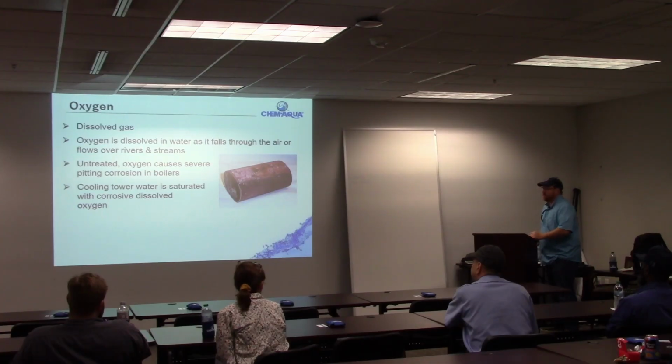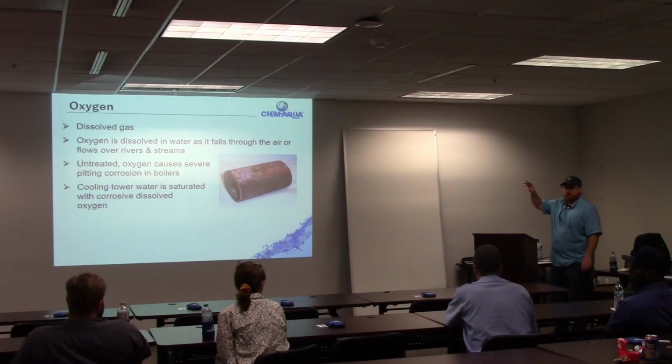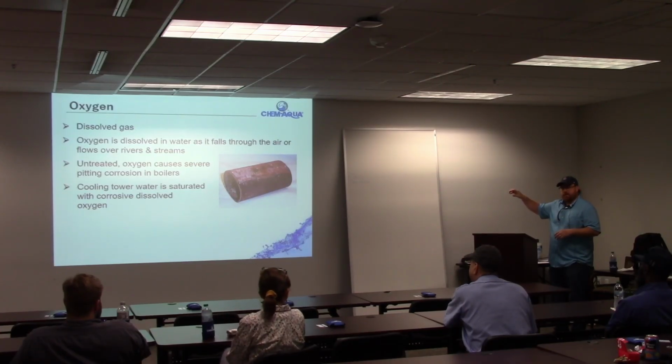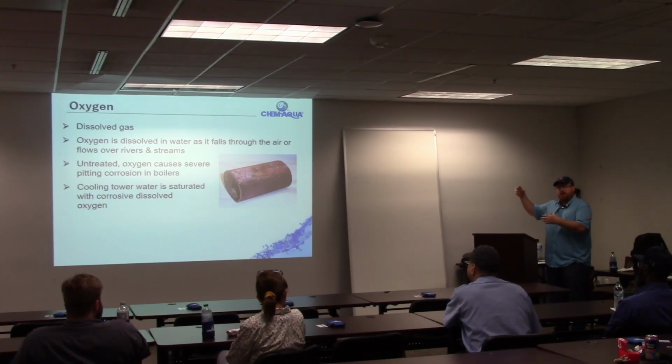Yeah, you will see PVC like that sometimes, especially downstream from where the chemical is injected, like a chemical injection loop. When you inject chlorine and bromine into high pH condenser water, you can have localized scaling downstream because of the interaction of the chlorine with the high pH, high alkalinity water. It will cause localized calcium precipitation in that line. That's a good preventative maintenance thing for engineers to be aware of, because it can cause flow issues through your chemical control loop for sure.